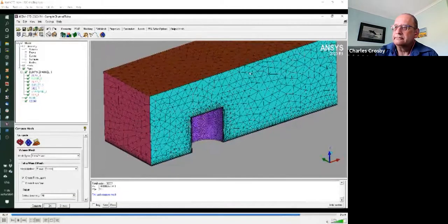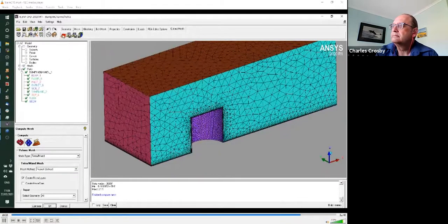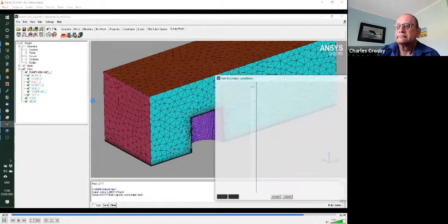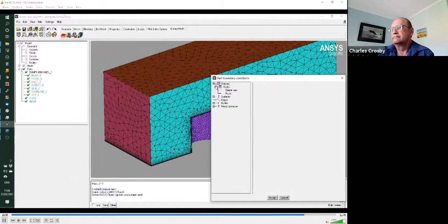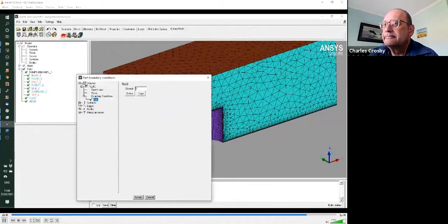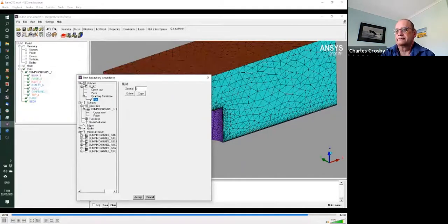Of greater interest is that you want to export this mesh now to some kind of solver. So we can select Fluent as the software that we're generating a mesh for. Fluent is one of Ansys' CFD products. And then most crucially, we're setting up boundary conditions. You would typically create a fluid for the body of the mesh, and then for the surfaces, the one-sided surfaces, there's a whole bunch of them here. They're popping up under mixed unknown. The way it interprets varies a little bit with the characteristics of the model.